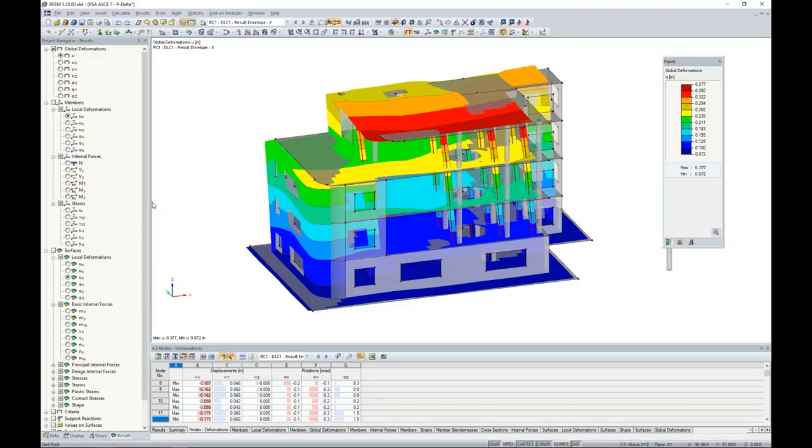And that's likely because my theta equation from the ASCE 7 is really, really small. So P delta did not make too much of an influence. But there are scenarios where P delta does need to be considered. So this is the effective way to do it within the actual calculation itself.